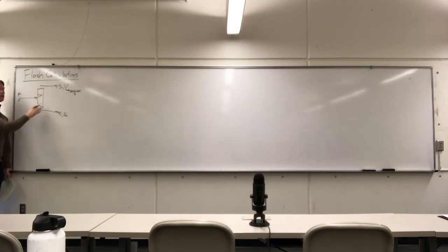The total quantity of each phase is done after the fact using a material balance, where let's say it's an I balance for species I, the total amount in the system, in equals out. Mass can't be created or destroyed if there's no reactions, which we're going to assume in just a simple separation process; moles aren't created or destroyed. So everything flowing into the system of species I is going to be the total composition times the molar flow rate of the feed, which is going to be equal to how much is lost in the liquid stream plus how much is lost in the vapor stream.